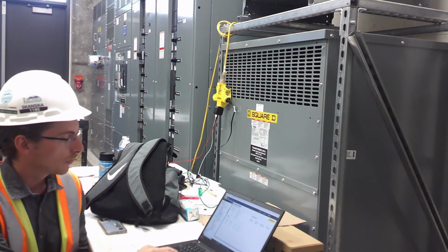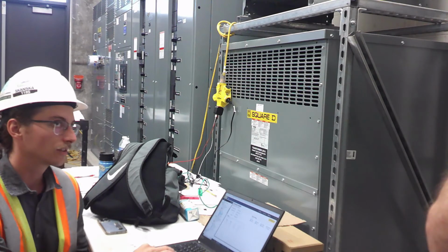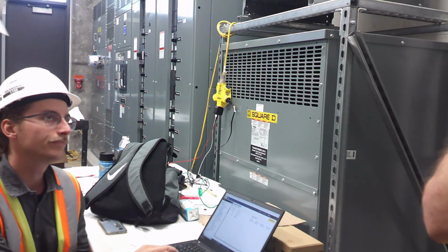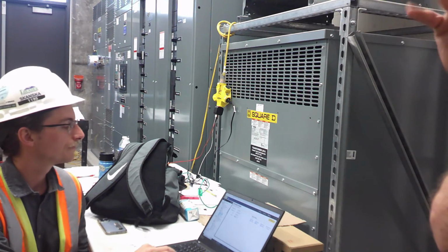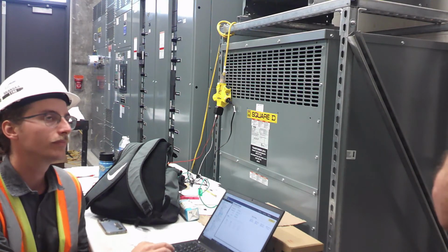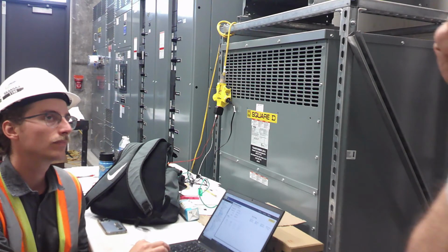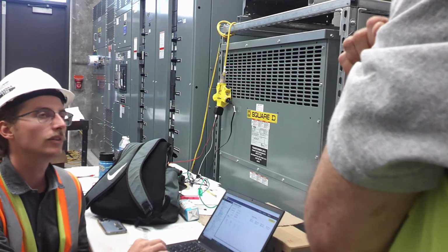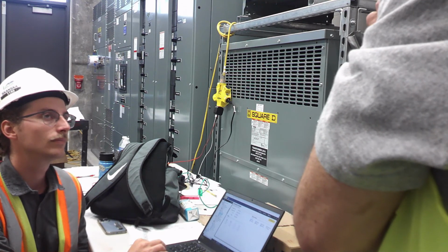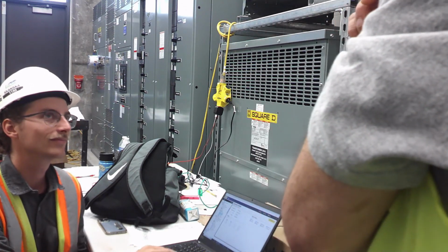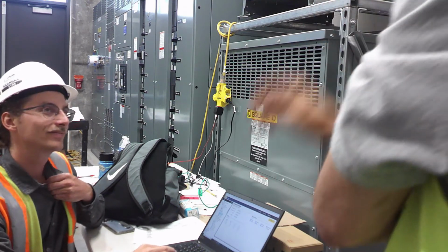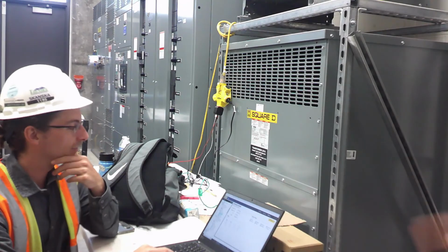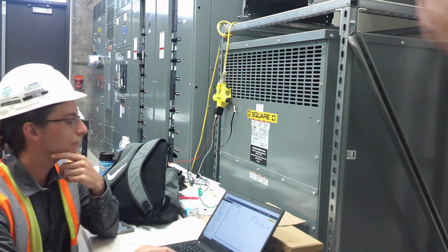What I would do if you didn't want them to turn off at midnight, I wouldn't delete the schedule. I would just change the action to be none. At the district office, they wanted to keep the lights on all night, I guess there was some security stuff. So I went into the program, and I thought, I can just delete these times and leave sunrise and sunset. I was getting ready to hit the delete button, and I went, wait a minute, how do you add a schedule? I didn't know how to add a schedule, so I didn't delete anything. I just turned off those 2 groups on the times, left it for sunrise and sunset, and walked away. Yep, that'll also do it.